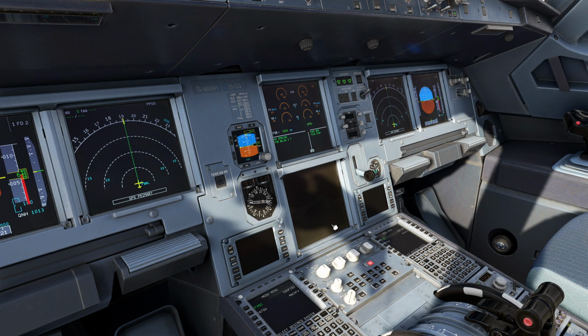With this selection, or if the system display unit failed, there is no change of this system display on engine warning display. Engine warning display shows the primary condition of engine as well as EPR, N1, EGT, fuel flow, N2, and many other essential parameters about the aircraft and also engines.